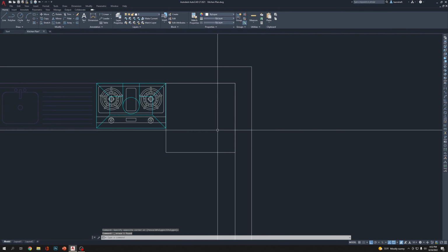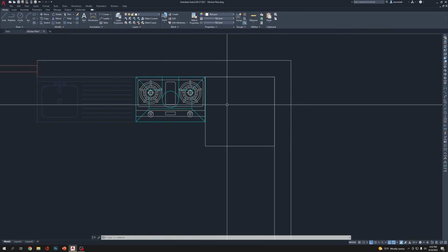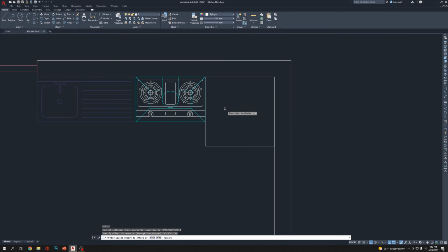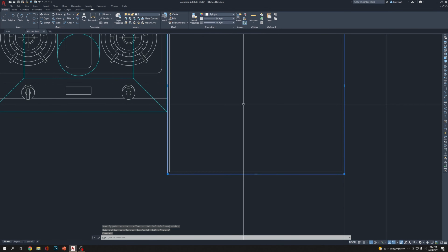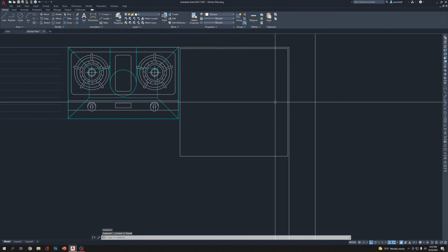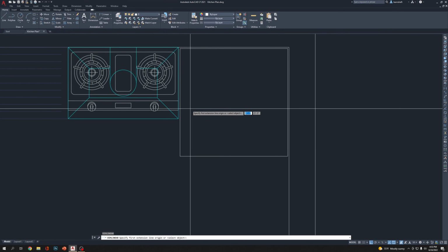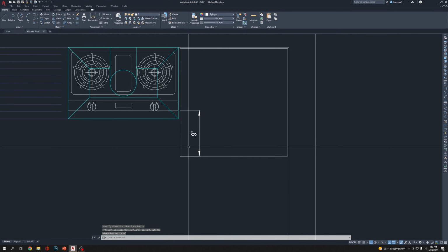The problem is if we make it as the size, it's not going to fit there, so you're going to push it, like make it have a quarter inch both sides, small. So offset, enter, 0.25, enter, and delete the first outline we had. Now let's say DLI, enter. Let's see how much is left from here to there. It's 9 inches.